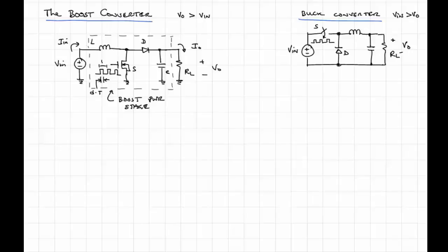And there is a feedback system. There's more electronic circuitry that surrounds this converter that will measure the output voltage and compare it to a voltage that you desire. We'll call it a reference voltage, much like the reference temperature in your home thermostat to regulate heat, or the AC to keep you comfortable at home. Same thing here. You have a voltage reference.